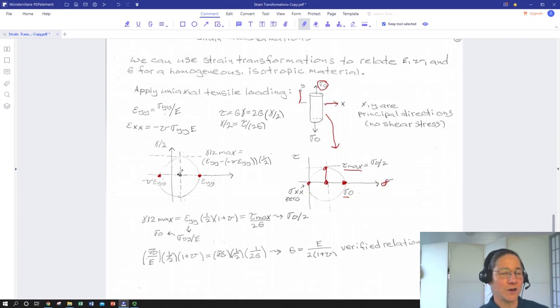And we'll have our strain Mohr circle center somewhere, and its max will correspond to the radius. Tau max will correspond to just the difference between our first principal strain and our second principal strain divided by 2. So first minus second, which happens to be negative, so it'll be plus second divided by 2. So it's just the geometry of circle center to get radius. So this is again our gamma over 2, or our tensor strain.